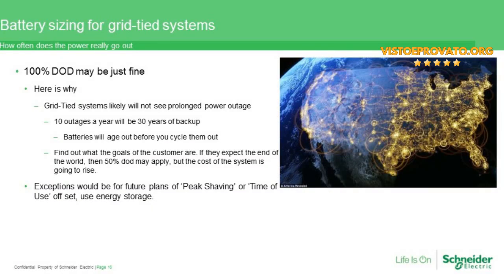Again, to reiterate some of the points that we've already made about the cost of the system and which way to start in the beginning, it's worth noting once more that typically a DC coupled system is going to have the best cost to benefit ratio, if you will, partially because here in North America, of course, we have our 30% tax rebate. And so being able to incorporate the batteries into that initial cost is going to have a huge impact on the overall cost of the system.